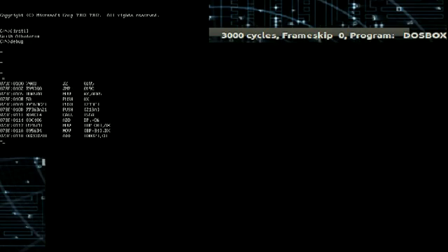The one below it, the jz takes 2 bytes, you know, because why? It's 7403. The jump command takes how many bytes? 3 bytes. E99700 to execute. And then we have the move command, which takes 3 bytes, B80500. Then we have the push, which takes what? Because I'm pushing the accumulator, it takes 1 byte, and then push again with what? How many? 1, 2, 3, 4. Why 4 bytes? And the previous one was what? 1 byte.